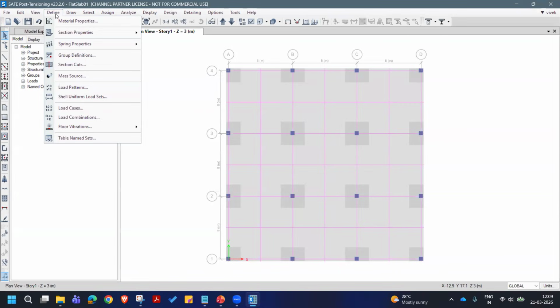Second option in that would be exporting the previously discussed plus loads from above, which is typically used for foundation system. But in case of transfer girder level or transfer slab level, then the loads from above acting on this floor also needed, then you'll use the second option for the export. Third option is only utilized when you are dealing with the temperature loads.